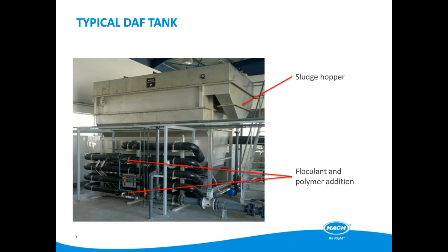Here we see a typical DAF tank where the mixer and floc formation zones are external to the DAF tank, within the serpentine black tubing. In most cases, this is the normal configuration of a DAF system. Separate flash mixers and flocculators are mainly reserved for the DAFs in potable water applications.